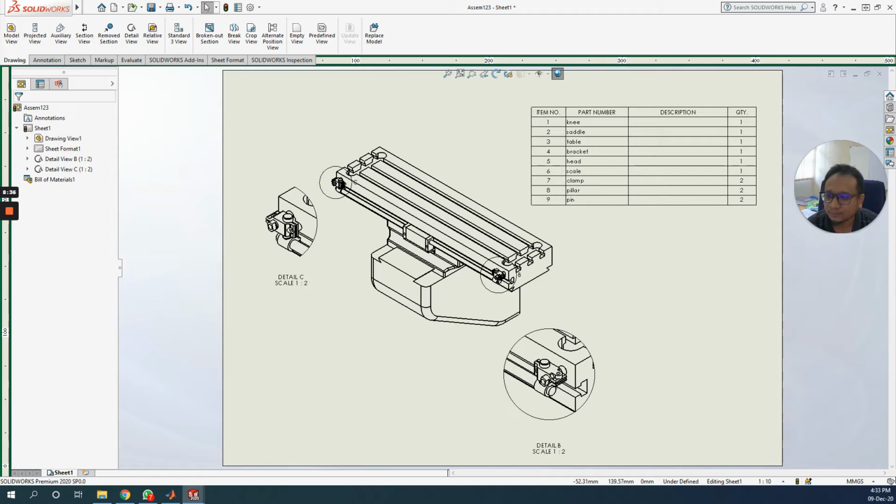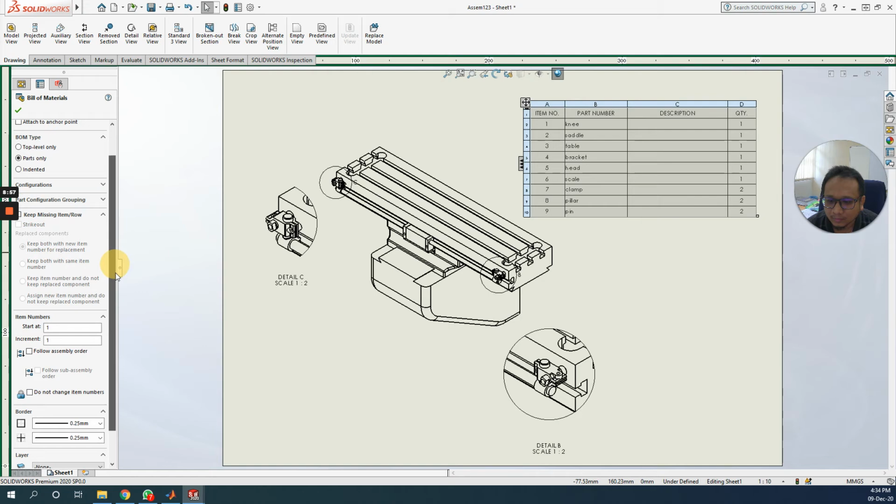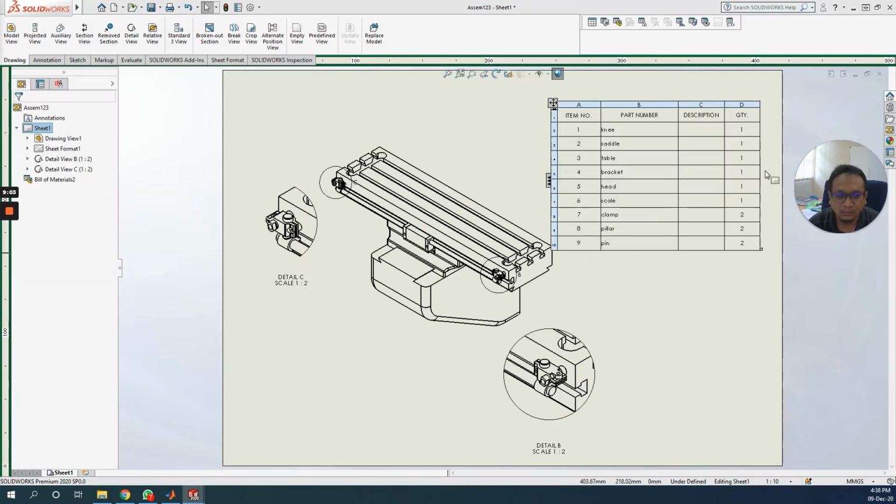Okay, so you can also increase the table by clicking this and increase the size as well. And then you can also customize it, select the price, for example the cost of the properties, okay, and click on layers. Now the bill of material table here, you can actually customize it by double clicking this here. You can customize this description, for example what you want, or you can use the custom properties to change the unit or the equations you want to add. For example, say you want to add the price equation,